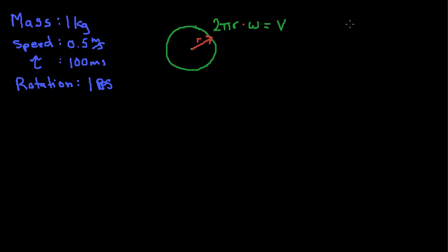Now, if you recall, a DC motor has a linear relationship between its torque and speed. Say this was torque and this was speed. Its stall torque is going to be somewhere around this point here, and it's going to have a linear relationship to the no-load speed, which is around here.